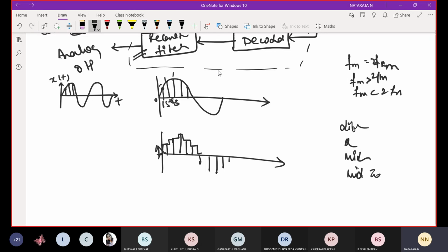For example, if it is 2 power 2, there will be 4 possible cases: 00, 01, 10, 11. For example, if I get a voltage level of 1, it will be equated to 01. If it is an amplitude of 3 volts, that will be equated to 11.